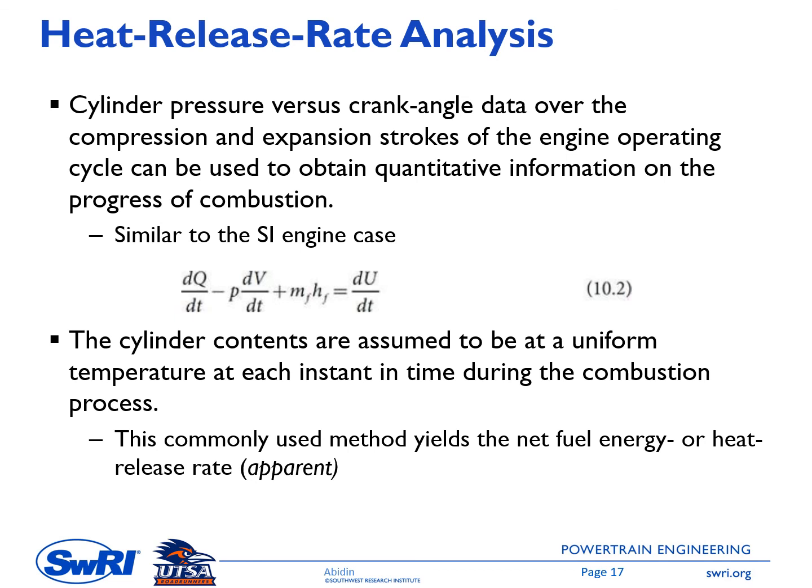So equation 10.2 is the first law of thermodynamics applied inside the diesel combustion chamber. This is the heat transfer through the chamber wall, and this is the work to or from the piston, PdV, and this one is the fuel energy, so m times h. H here is the lower heating value of the fuel, and du/dt here is the change of the energy of the mixture inside the chamber.